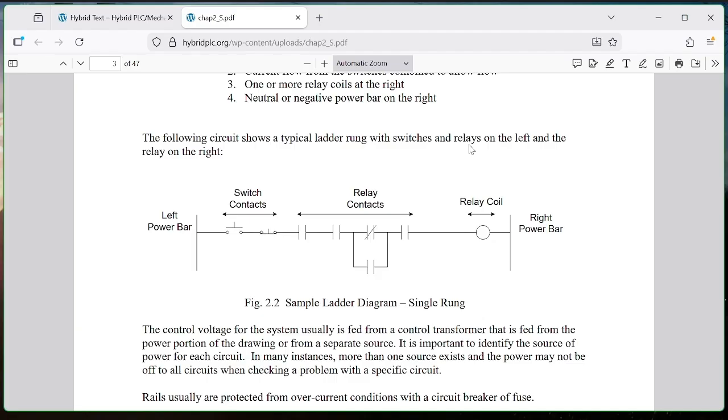Okay, this is normally open when there's no current, but the contacts change when you energize the coil. So at least you get a little bit of an idea what's going on. This is a motor starter. Does the same thing. Coil, closes. But this has contacts that are rated for a motor. Same exact thing, except the contacts are a little beefier.